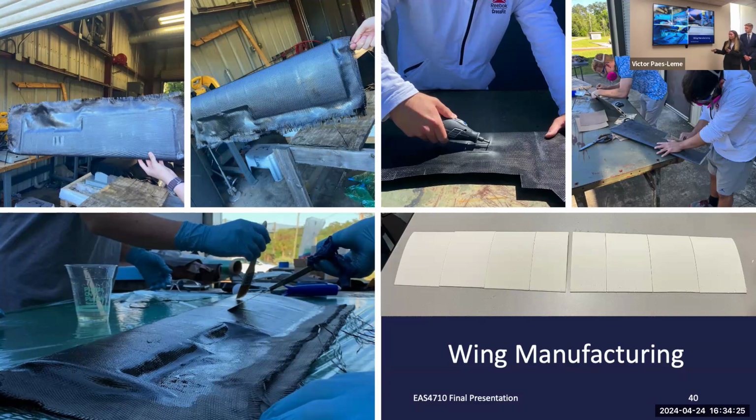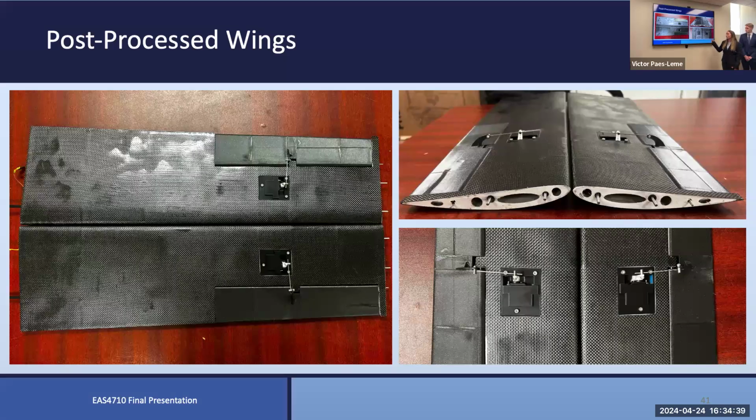And from there, we took it to Solar Park and did a carbon fiber layup, just 1 layer, that we epoxied and let cure for the weekend, and did some post-processing of that as well. And here is the final product of the wings. This is also with the ailerons and the servo motors attached to it as well.